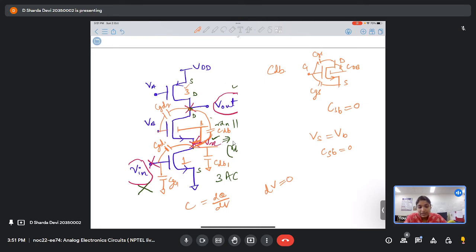Okay, there might be another condition. Ideally, when you are designing your circuit and laying it out, you only have one body terminal for all the NMOSes and one body terminal for all the PMOSes. Generally that is the idea. So what we do is connect the body of NMOSes to ground and PMOSes to VDD, right?